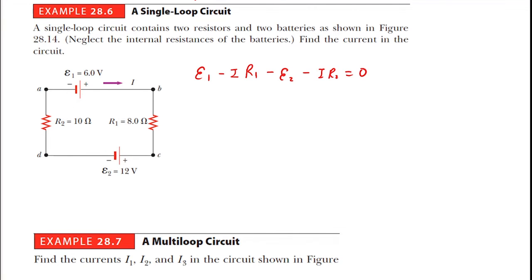Okay, so here's the rule. Every other thing, resistor or capacitor, if you go through it, you just drop the voltage when you draw the loop. The only thing you have to care about is that everything is minus except batteries. Batteries, you have to decide a little bit carefully. Are we gaining potential or are we losing potential? This is gaining if you go through this way, low to high, compared to high to low. That's the only thing we have to be careful about.